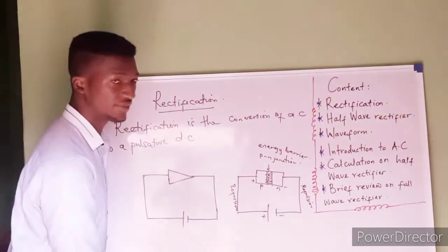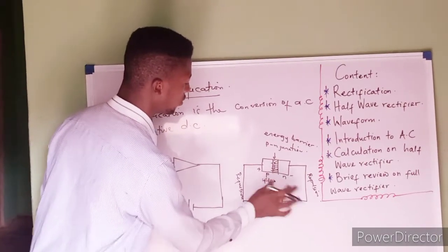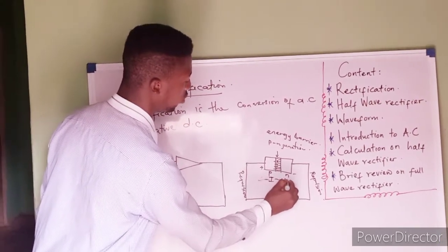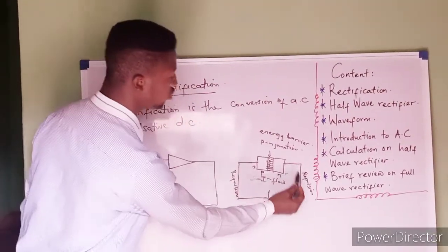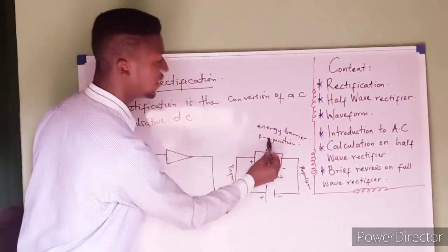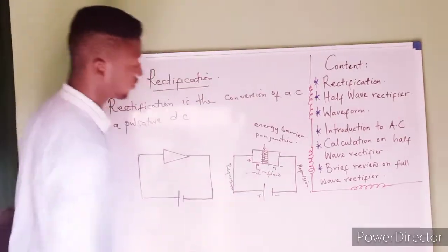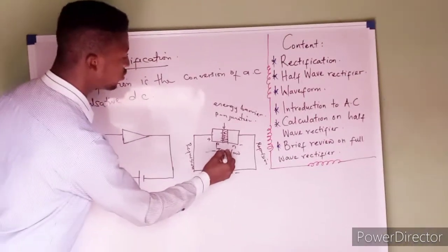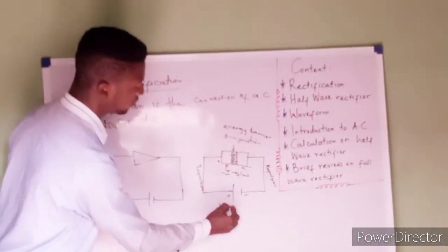This region now is leveled, and as a result of that, current can rapidly flow. The reason current flows here is because the electrons jump into the P-N junction, and it reduces the energy barrier. And as it reduces the energy barrier, they allow current to flow through. So this is what we refer to as biasing of diode. When current flows through, we call it forward bias.